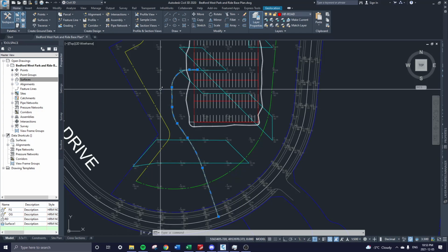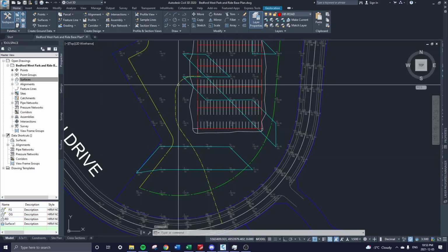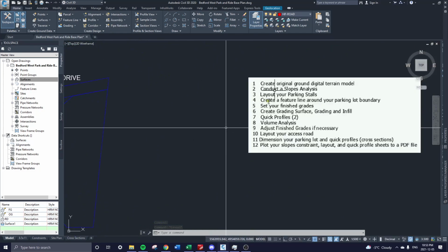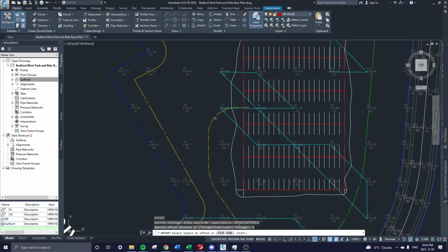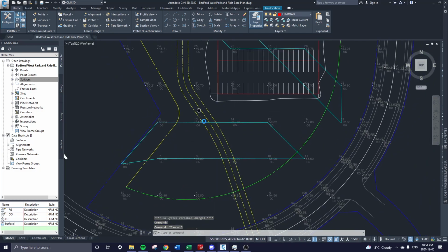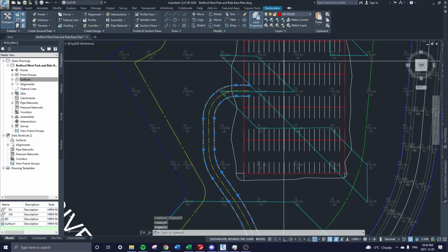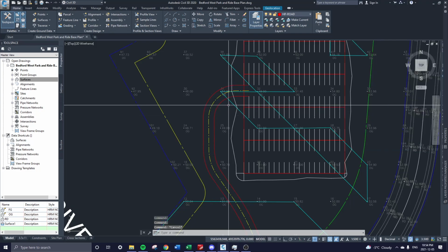of our road. I don't think we actually have to grade this. So Paul has asked for, I believe, a 6 meter wide road. So you can offset that 3 meters on each side. There you go. And that's going to be your road on each side. You can change the side of it to match, maybe we'll put this in red and change the line type again to continuous.